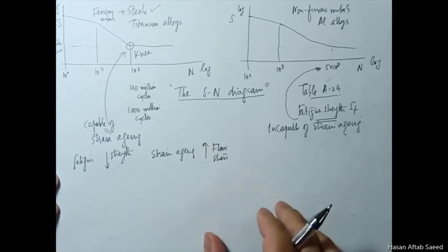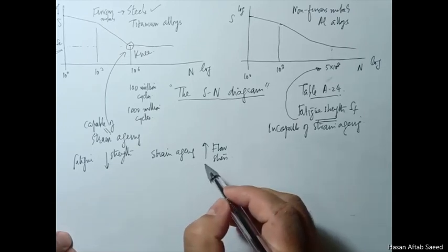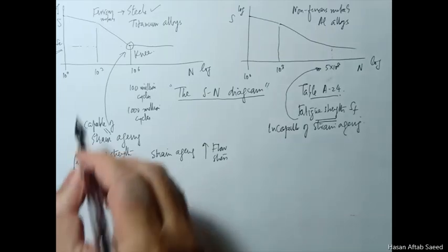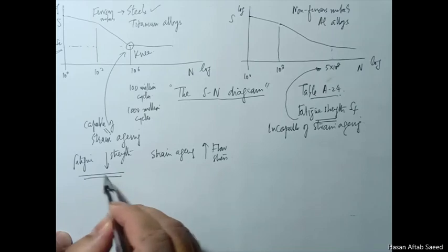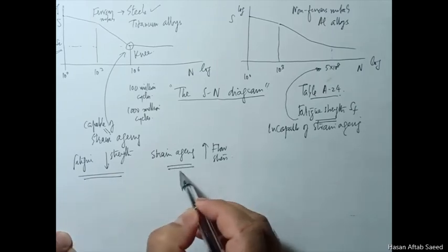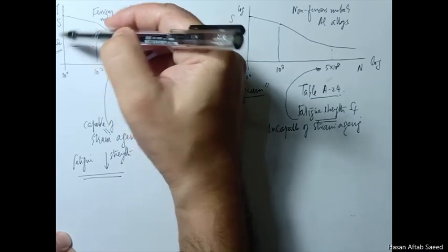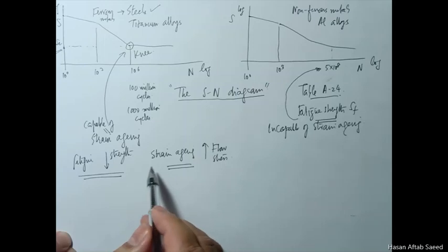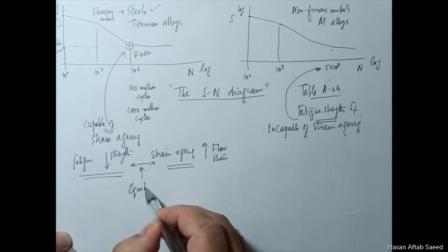It is as if in every cycle the yield strength of the material keeps increasing slightly, but it keeps increasing. Now, at higher stress levels here, it doesn't matter because fatigue always wins over this one. But there comes a stress amplitude level at which this starts competing, and the two are in equilibrium.